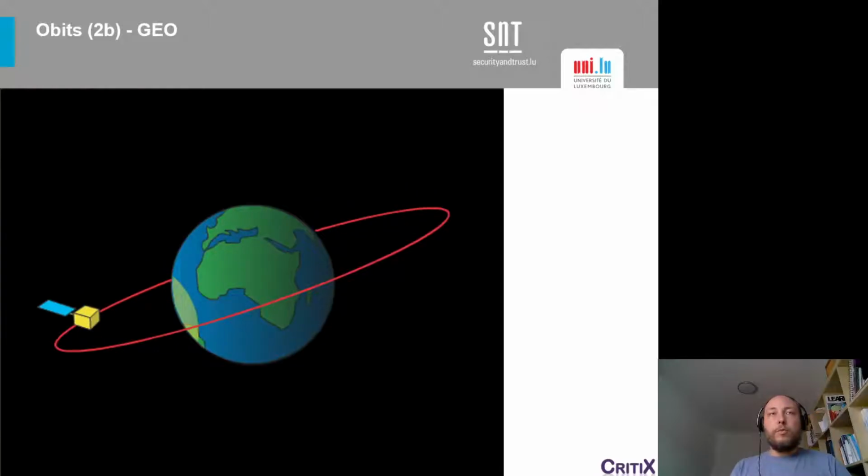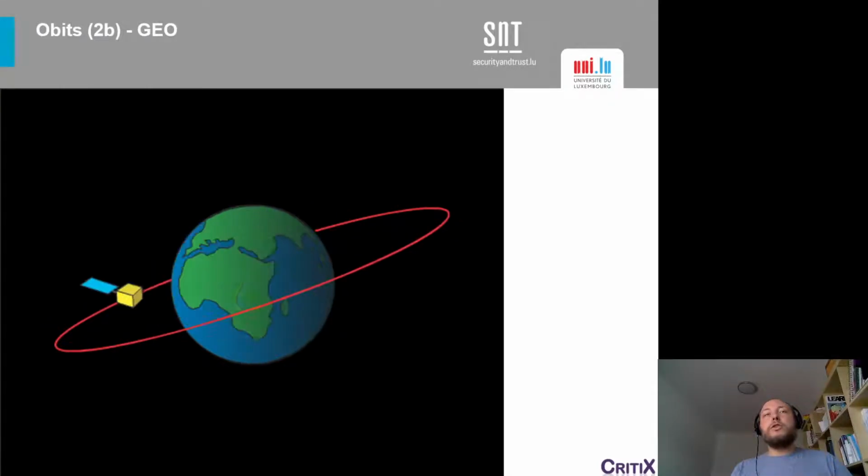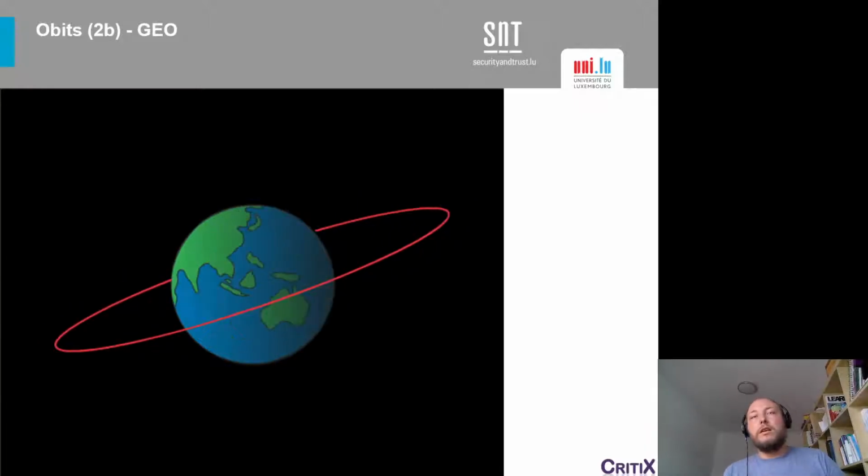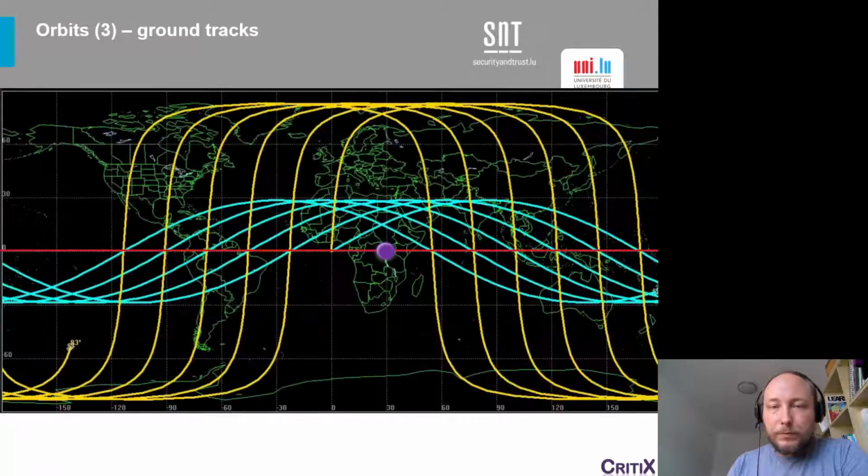If we decrease the inclination of the orbital plane, we start to talk about lower inclinations or equatorial orbits, which can be useful for telecommunication purposes, because then the satellite does not have access to the whole surface, but instead is visible over certain regions, which is useful when you want to use the satellite as a telecommunication relay. So here are the ground paths of such orbits.